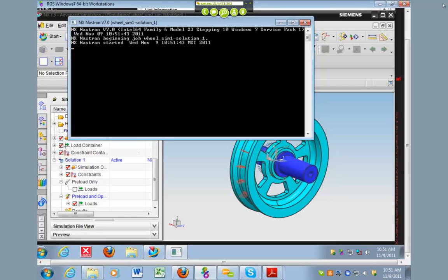The one difference between last week and this week is that when you have multiple parts, you just have to make sure you constrain them or have contacts, gluing or surface contacts, and then you're able to run an analysis on several parts, on a whole assembly rather than one part.